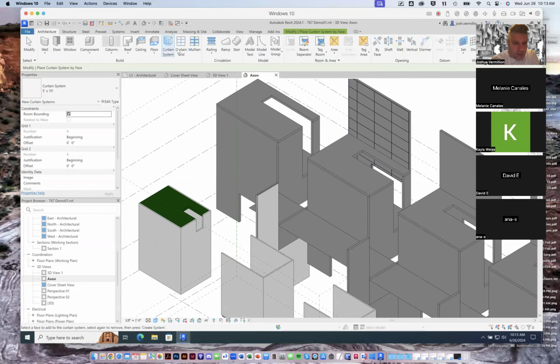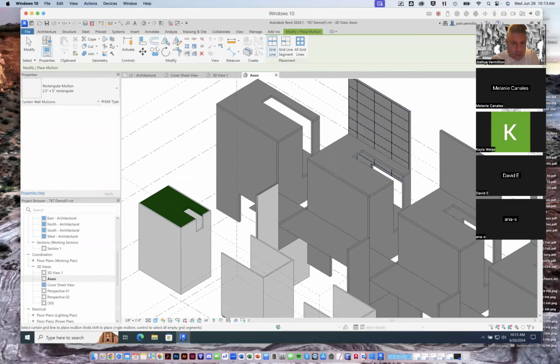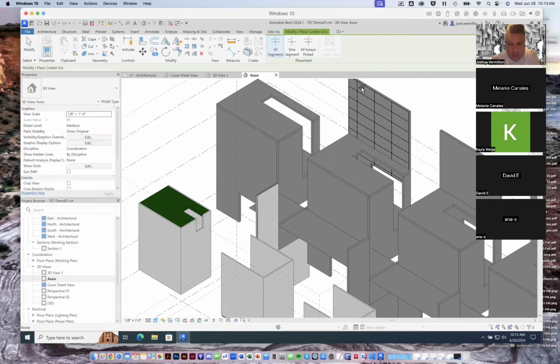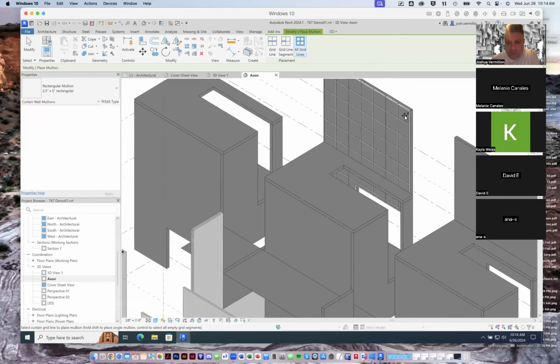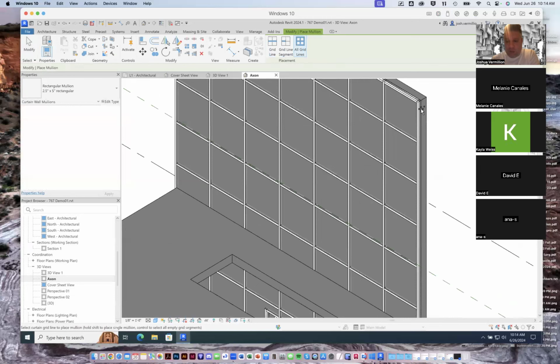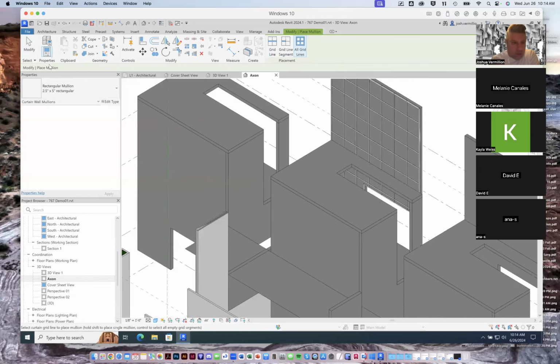Now you can see that with this thing selected, I can start to add mullions, I can change the grid, etc. All segments, one segment, you can say all segments, and then say mullions, all grid lines, and then give it all mullions, right? So that's simply taking my Rhino model and deploying a curtain wall on one of the faces.